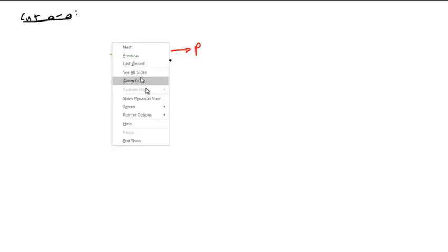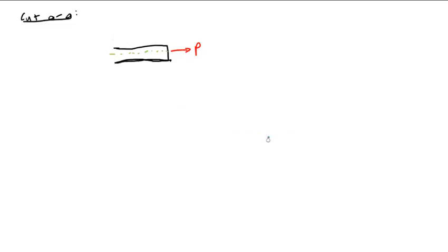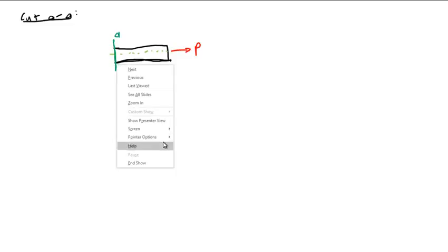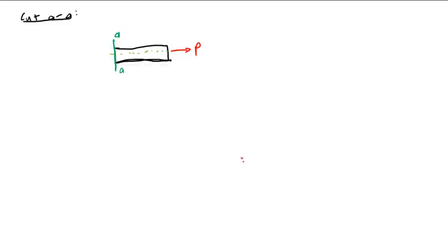Well, let me show the cut here. So I'm going to have A, and I'll have a shear, a normal force, and a moment. Shear, normal force, and a moment. And notice I am drawing each of these assuming positive by our basic sign convention.